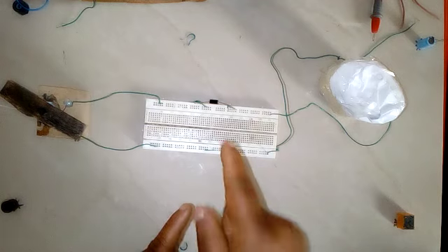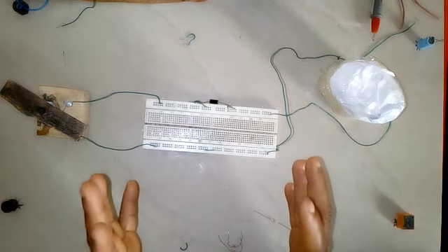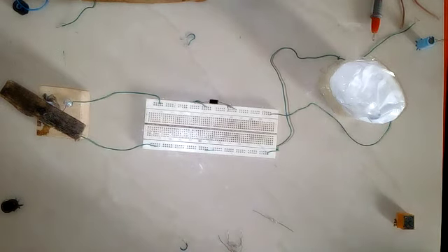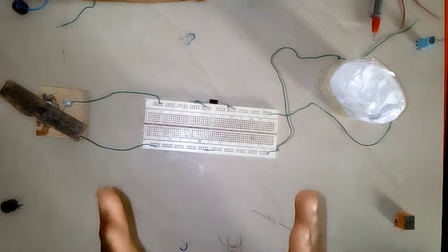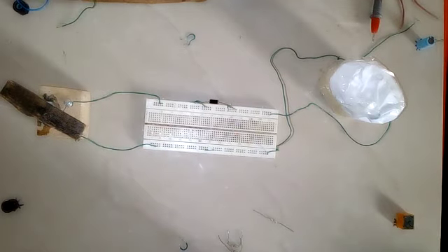What it means is that this diode is robbing us of 0.7 volts, which is quite significant in the circumstances I have painted. So on that limitation, we say this design is not a very good design because it robs us of 0.7 volts. An alternative is to connect it in parallel to the DC motor. Let's try it and see what becomes of the circuit.